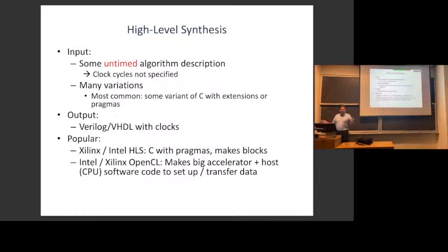And that will run on either a hard processor or a soft processor or maybe an x86 processor across the PCIe bus, and set everything up and just do the lower bandwidth computations. So the nice thing about OpenCL is it lets you write all that in one unified program that is fairly standard, rather than having to make it all up yourself. Does that make sense?